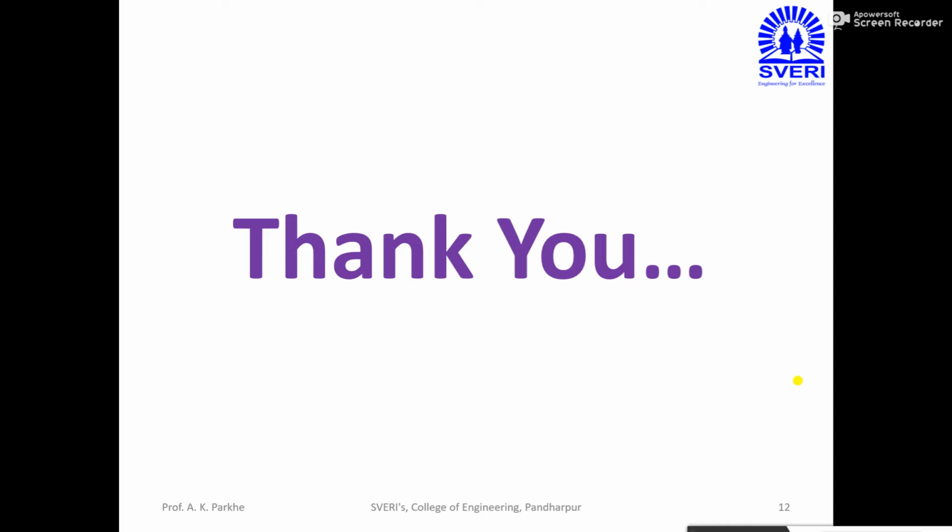and from these three values I have to calculate all the remaining unknown parameters. In most, about 90% of problems, they are giving the values of epsilon a, epsilon b, epsilon c, and sometimes epsilon d. Only 10% of the time they give the direct values of epsilon x, epsilon y, and gamma xy. If direct values are given, there is no need to refer to the table. Directly by putting these three values in the formulas we can calculate all the unknown parameters. But if the given data is in the form of epsilon a, epsilon b, epsilon c, then we have to refer to the table, calculate the values of epsilon x, y, and gamma xy from it, and then find out the remaining unknown parameters.